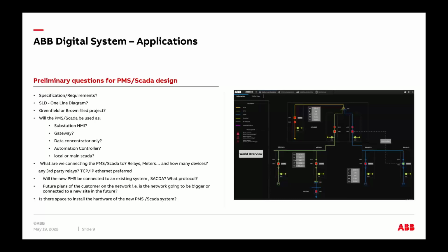So you need to duplicate that to a bigger software where you pull, for example, substation 1, 2, 3, 4, and the main one will be on top of them, and you're pulling data from all those 5 sites. So again, you need to ask yourself, how many devices do I have to monitor? What kind of devices are they? What type of communication protocol do they have?